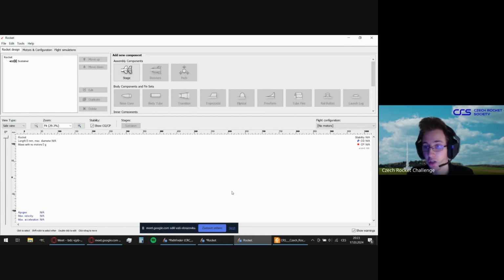We also want to have some onboard flight computer, some avionics. Here, it's just an estimation, but for example, we estimated, okay, we'll need this flight computer and this chip for the ground station communication, and we want to measure this and this, and all together, it will be roughly like 100 by 40 millimeters, 75 grams. This is just a rough estimate. I advise at this point to make really conservative estimates. It's better to design it a little bit bigger and a little bit heavier and then scale down than the other way around.